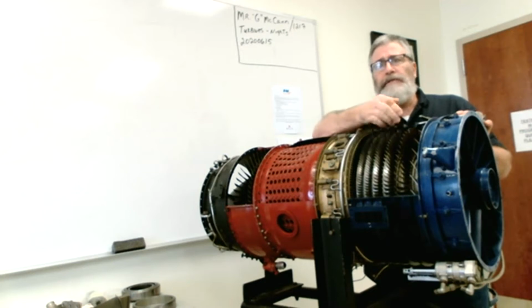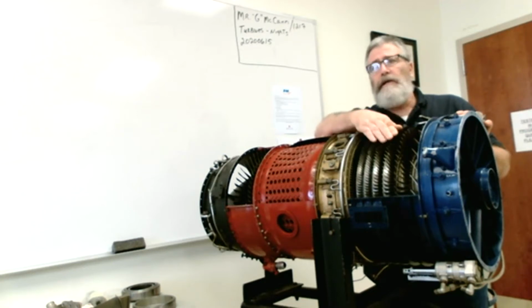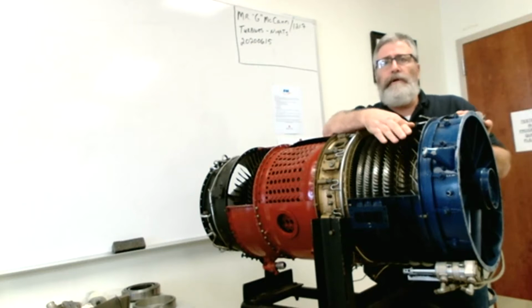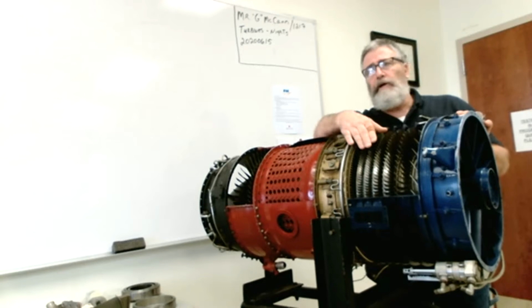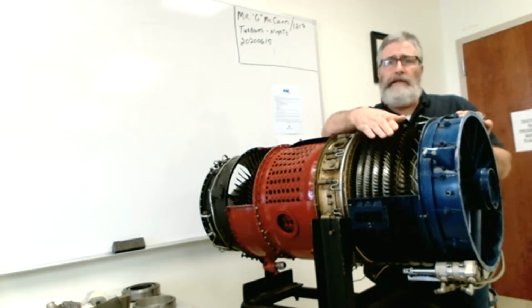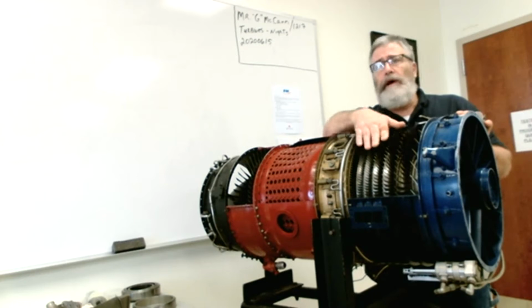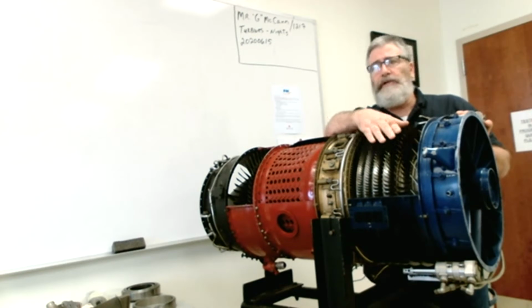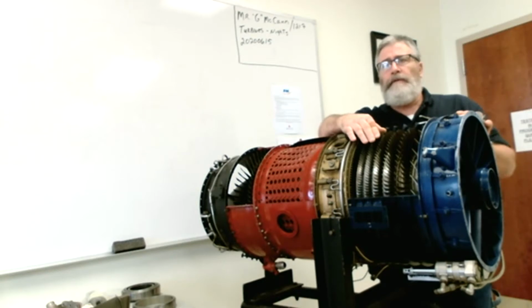In the event that the tips actually contact the case, the damage would be negligible in most cases, all right? So remember, what is a profile blade on an axial compressor? It is a blade that is thinner at the tip, or you might be asked, what is a compressor blade that is thinner at the tip? And that is a profile type blade.